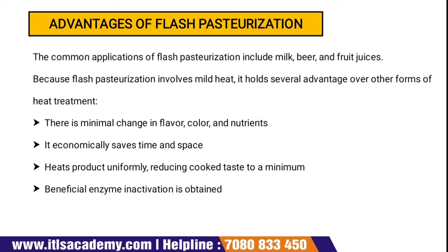First, there is minimal change in flavor, color and nutrients. Since the temperature is low, there is very slight change in flavor, color and nutrients. It economically saves time and space. Then it heats the product uniformly, reducing cooked taste to a minimum. Then beneficial enzyme inactivation is obtained. So these are the advantages of flash pasteurization.